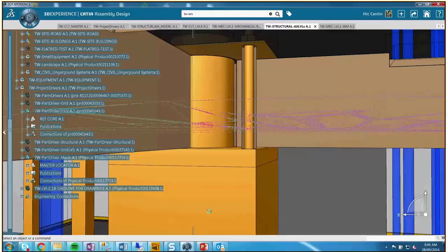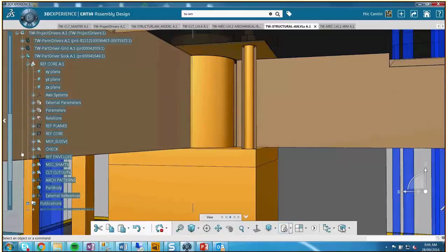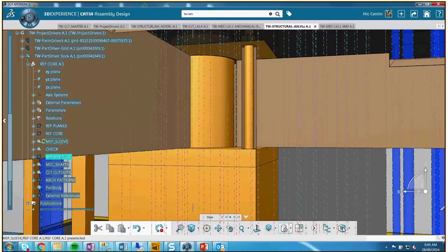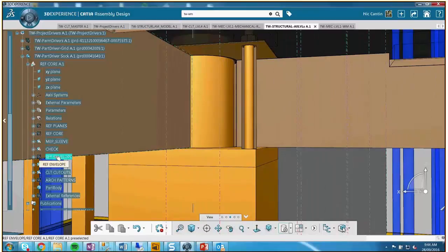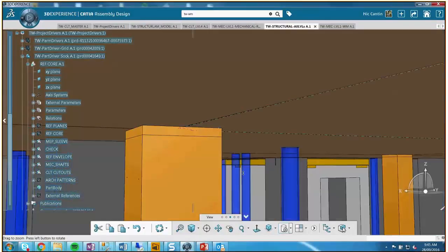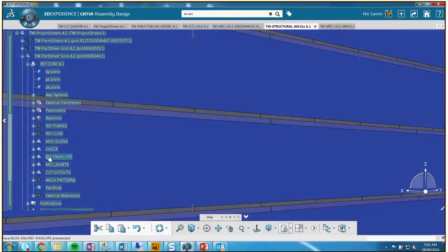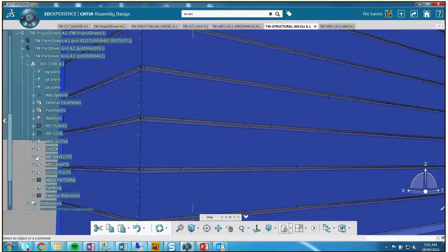Sure, mechanical. Are they prefabbing the interior walls in the next iteration? We actually have another one we're just starting, and that's our recommendation so far: to try to find a solution where the wall is fabricated with pipes in it and maybe one level of gyp on, so the plumbing code inspector can review on site, but at least you just have one side of gyp to close off. But there's a tolerance on the top track that I think is a challenge if there's a slab above when you're installing.